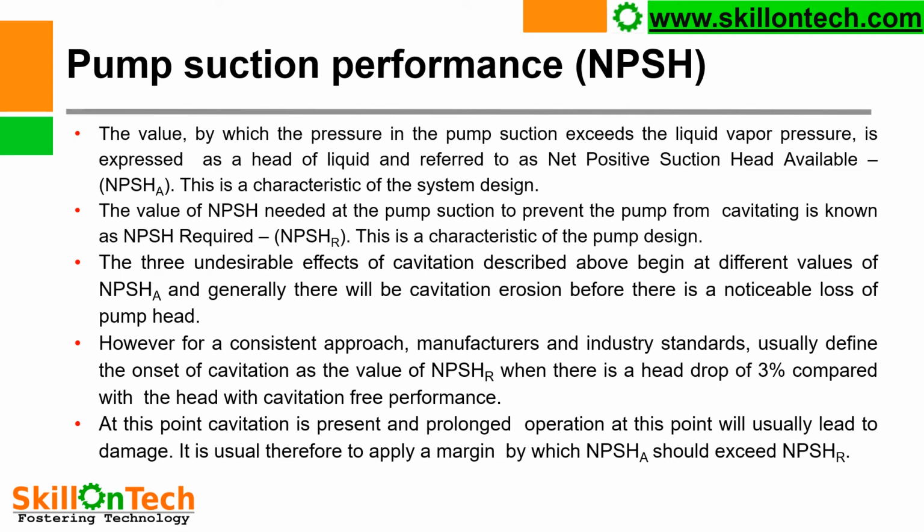At this point, cavitation is present and prolonged operation at this point will usually lead to damage. It is usual therefore to apply a margin by which NPSH available should exceed NPSH-R. So in all cases, the NPSH available should be more than NPSH required to avoid cavitation in any manner.